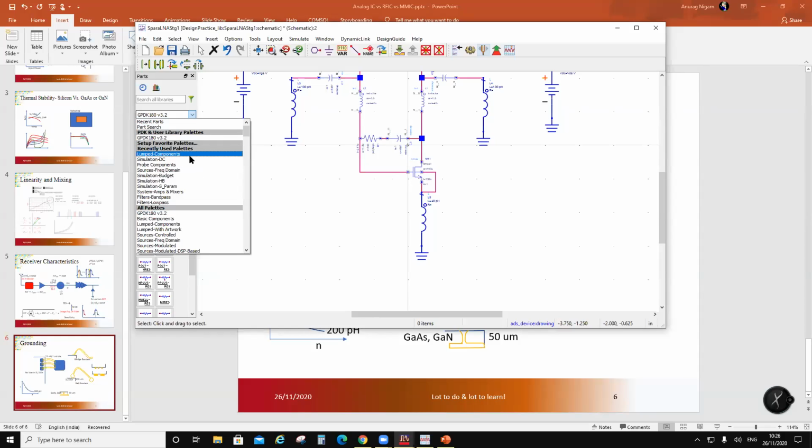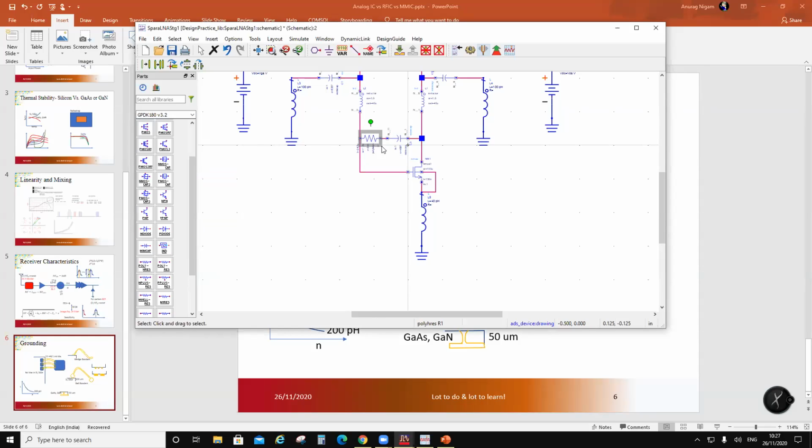UMS come out with a power bar. And you will see in that power bar, or anybody else who is doing this gallium nitride, they sample you a transistor and then they give you an application note, and in that application note they say, to stabilize this, put a 3 ohm resistor here in the RF path. Yeah, it will kill the gain.